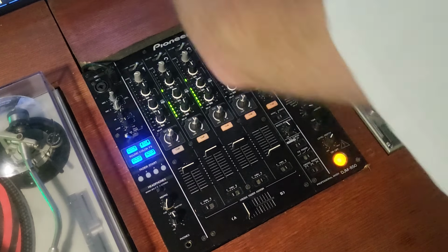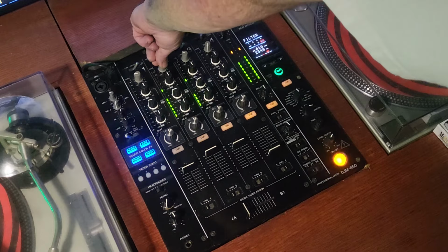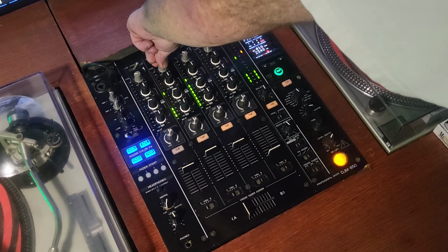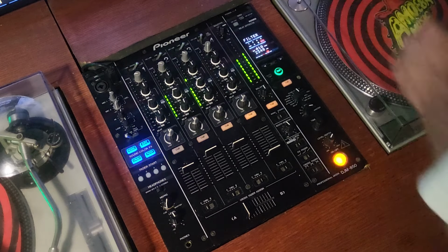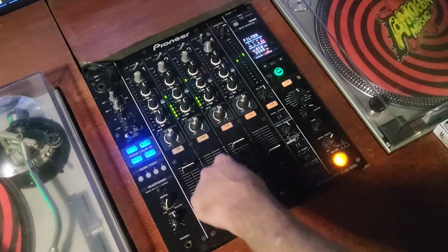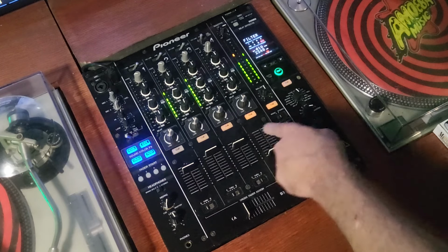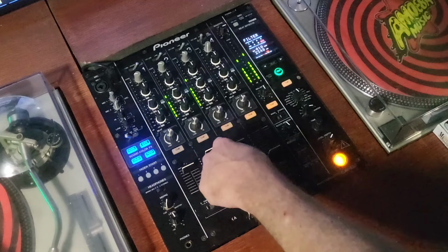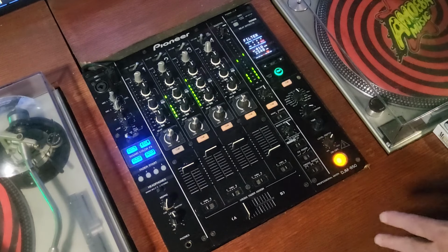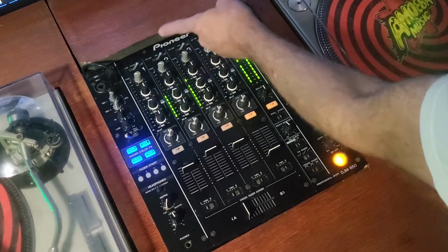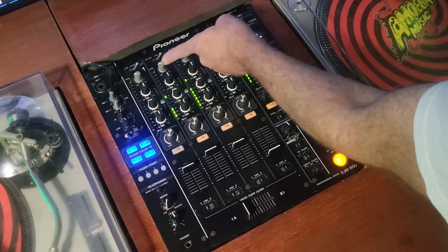See, we're there in the amber. If we bring the trim or gain down a little bit, like so, we're still hitting 0 dB, all right? And so no matter what you do, you hit 0 dB. You don't have to worry about this 8 position on the line fader. Here's the problem with that. You're not getting the cleanest input signal through your trim or gain.